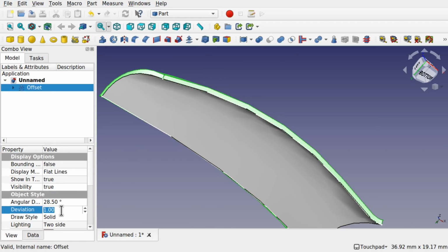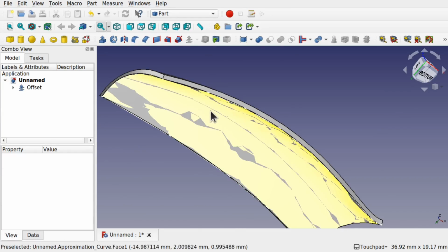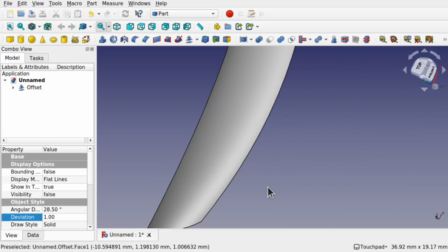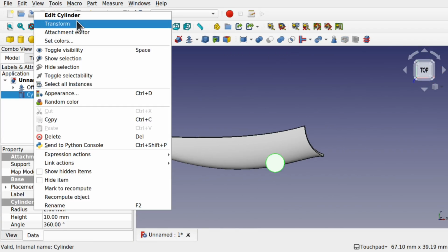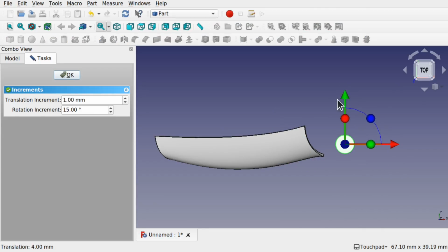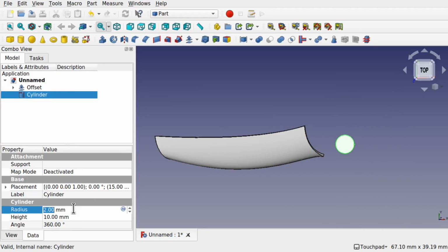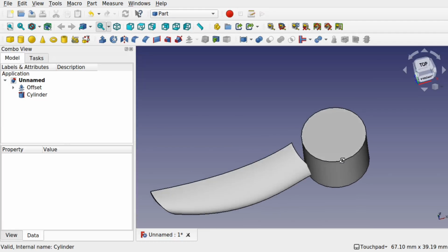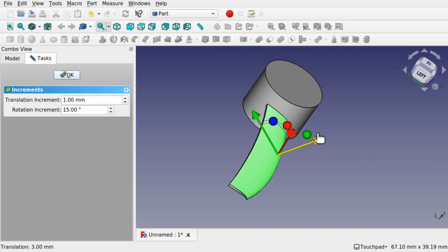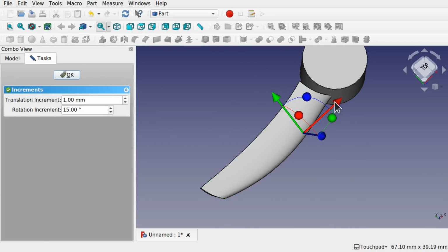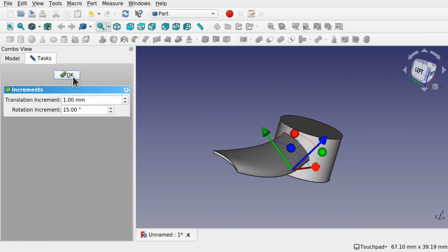The part design only allows you to create features that create solids. So the following video shows me going through actually taking that propeller blade and creating it into something a bit more coherent, so an actual propeller for a toy. You can see how I've created a primitive object and I'm positioning that blade on that primitive object ready for the Boolean operations in the future.